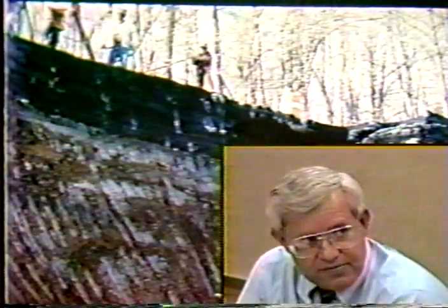Let's look at a case history where there was a problem. A shear trench was a solution. What you're seeing there is about 12 feet of asphalt. In a situation like this, and this is one of the purposes of this course, don't start patching a landslide and adding this much material. If you've patched over 2 or 3 times, and I want to emphasize this, you've most likely got a problem, and you need to start looking for the causes, and that's the reason we had a session on causes.